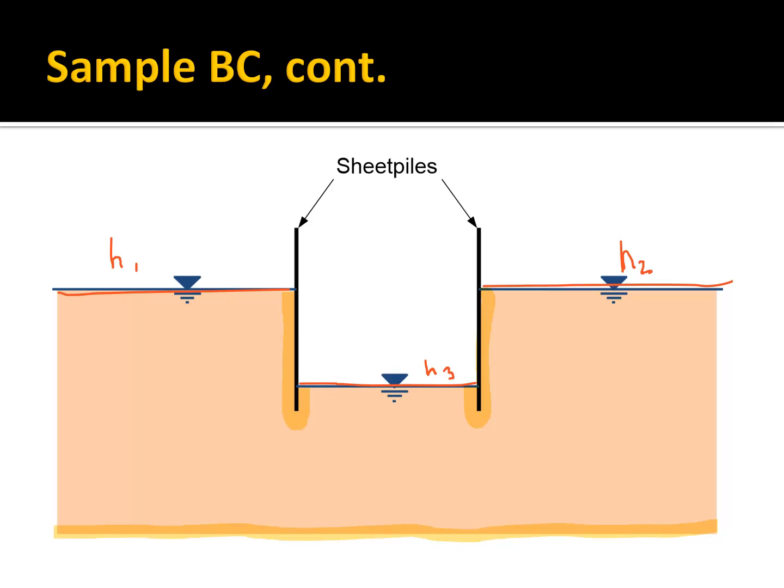along the bottom here. Now over on this left side, if you extend it far enough out, you can give it a head boundary condition equal to this height, or just a no flow boundary condition. And typically we just go out far enough, we can consider it a low flow boundary condition, because most of the flow is going to occur right down here, right around the tip of that sheet pile, okay? And over here it would come down and up this way.